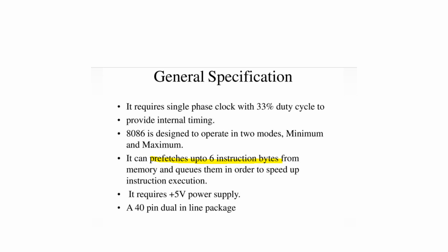So when it is taking care of the first instruction, it won't worry about the second instruction. But in 8086, while executing the first instruction, it starts fetching the next instruction, doing the opcode fetch of the next instruction. That means the completion of a program is easier and quicker than in 8085.